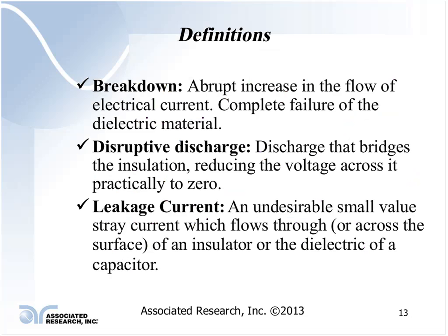Some standards may call for using a 120 k ohm resistor for setting the trip sensitivity of the Hipot. That's very common. Household appliances for a routine production line test tell you to set the current trip anywhere from 5 to 30 milliamps. Why such a big variance?